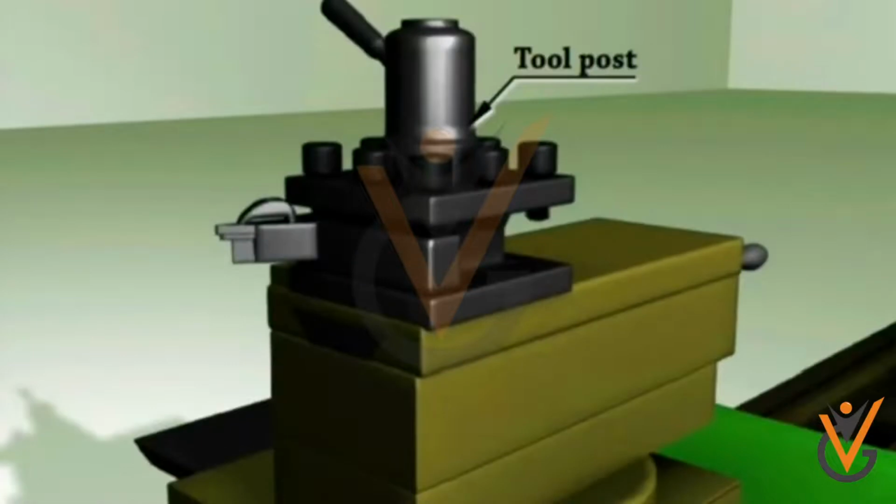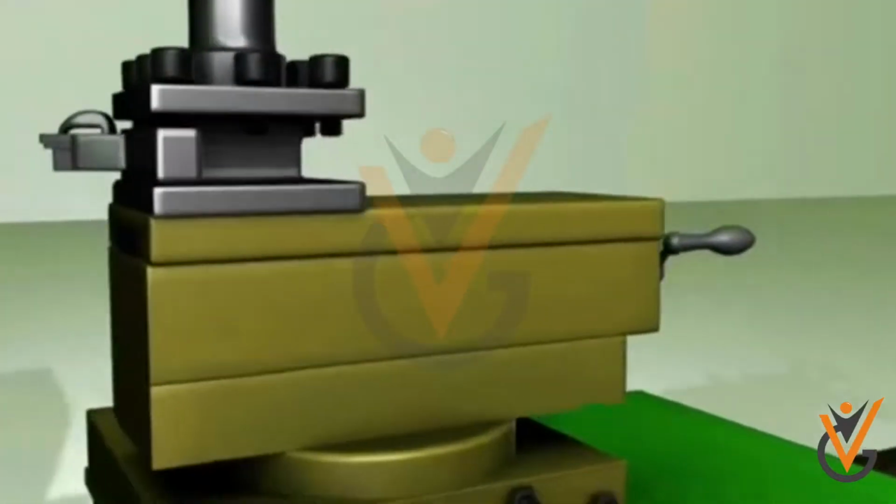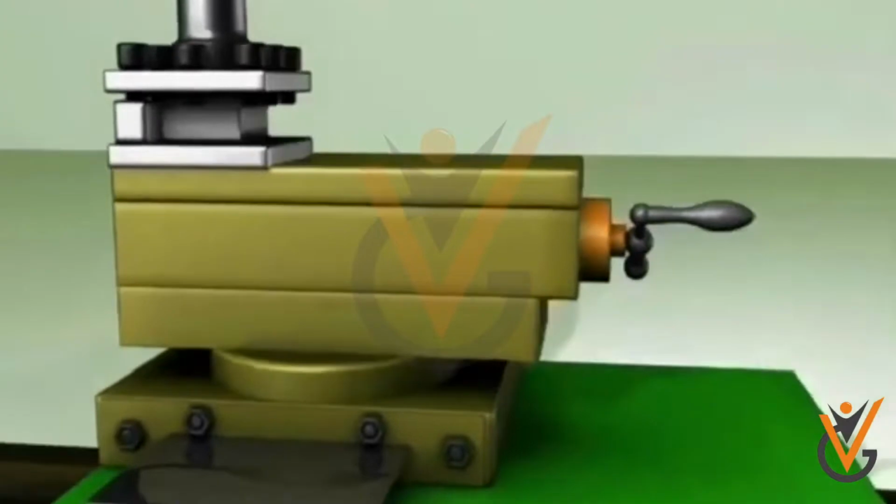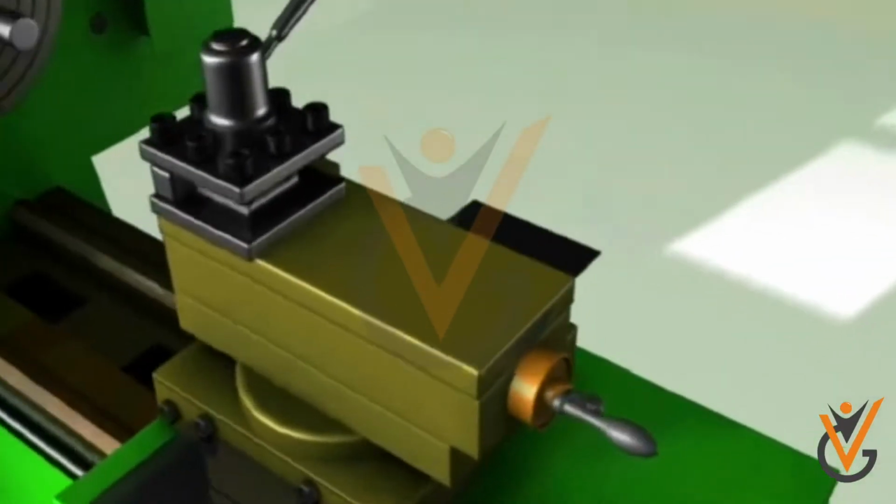Tool post. The tool post is mounted on the compound rest. It is used to hold various cutting tool holders. The holders rest on a wedge which is shaped on the bottom to fit into a concave-shaped ring, segmental type, which permits the height of the cutting edge to be adjusted by tilting the tool. It is fixed on the top slide. It gets its movement by the movement of the saddle, cross slide, and top slide.